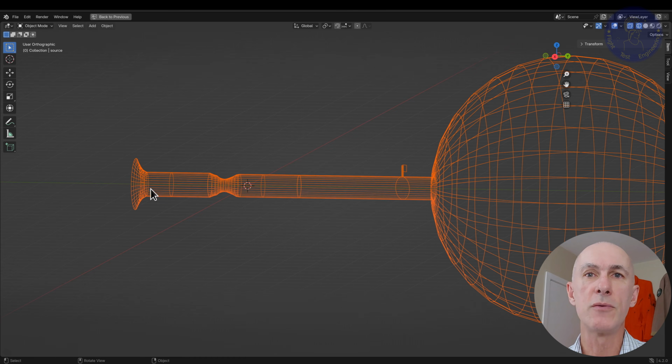So as we open the valve and the particles start to accelerate, are there any limits to what will happen? If we fully open the valve, are the particles going to accelerate indefinitely, or from your intuition, are they going to stop at some point accelerating and reach some sort of equilibrium? Well, it turns out there is. And what happens is that the pressure drop traveling upstream from the vacuum side can only go as fast as the speed of sound. Remember that sound is nothing more than pressure waves.